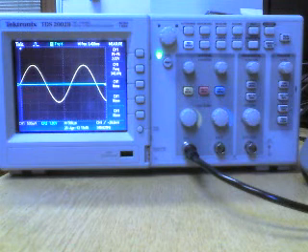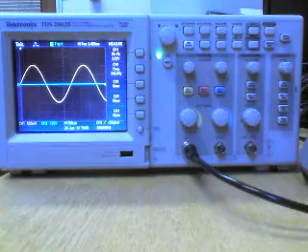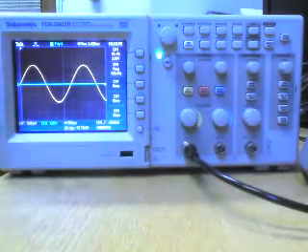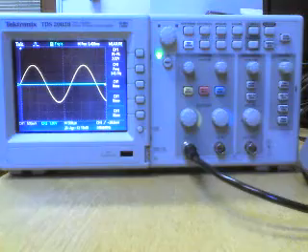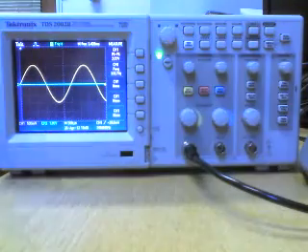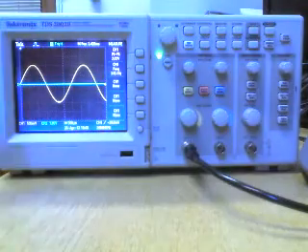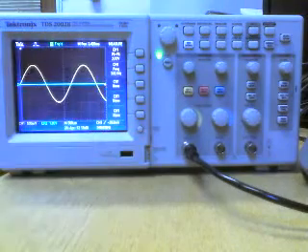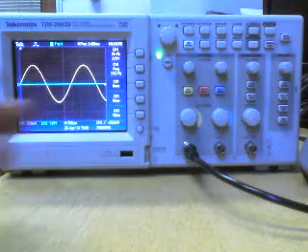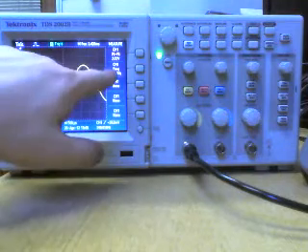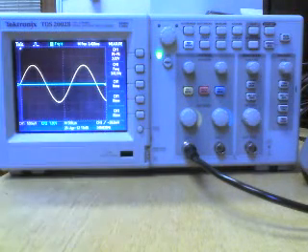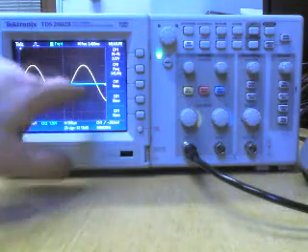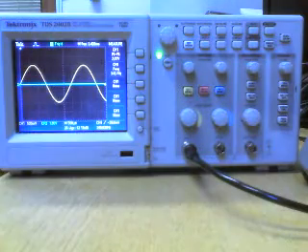Okay, so it's up to you which way you choose, but always use the same way of measuring throughout your experiment. If you start to measure manually, measure manually all the way through your experiment. If you want to use the measure function, then use the measure function all the way through the experiment. Otherwise, if you have any error in your manual measurements and then you decide to start using auto measure, you can end up with a huge error between the two. For example, I measured it manually to be 333 Hertz when this is auto measuring it at 340 Hertz.